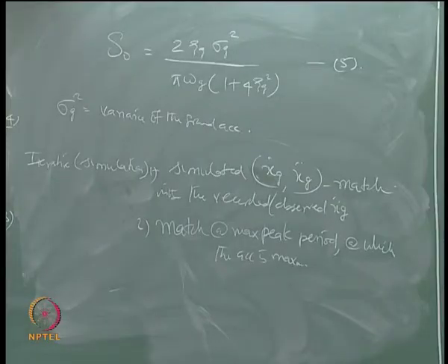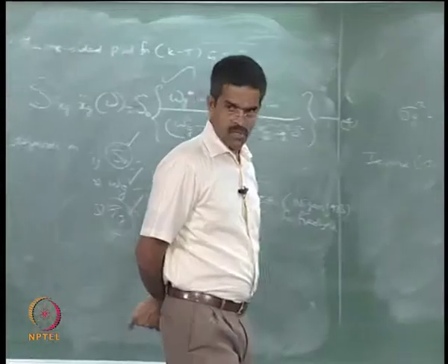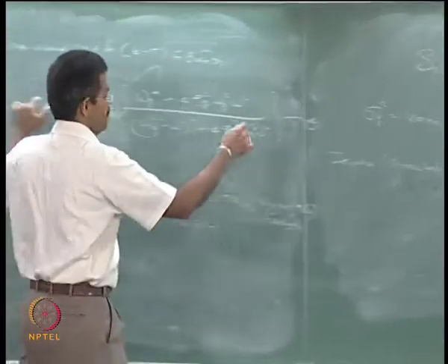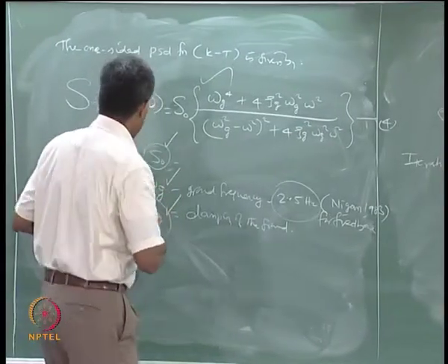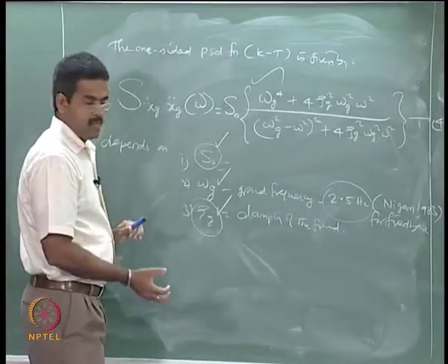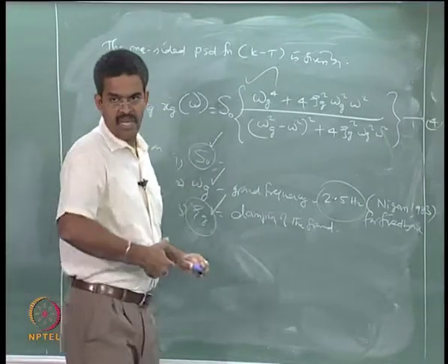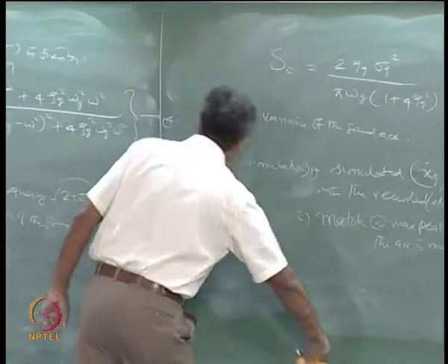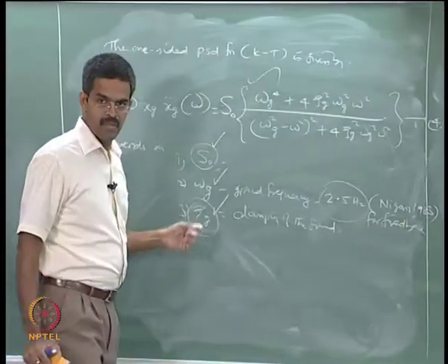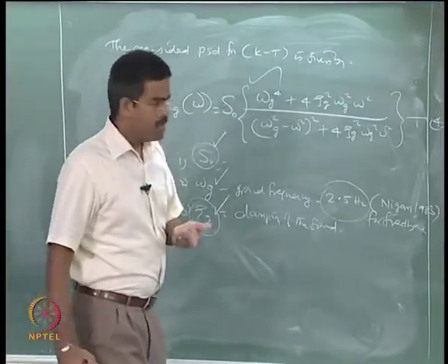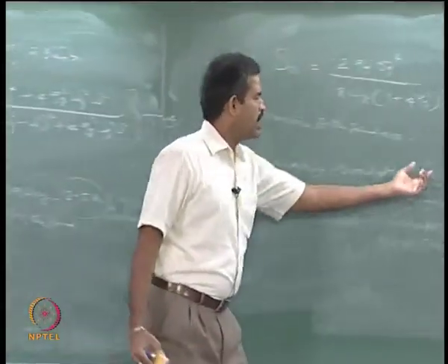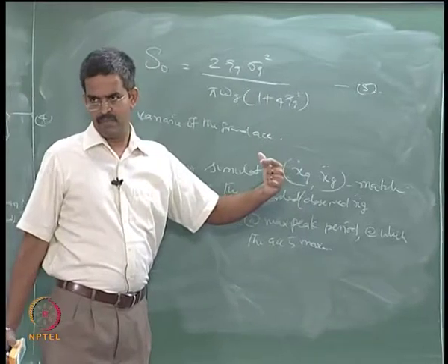So, seismic loads are not direct. Though you have a spectrum, the spectrum depends on 3 parameters. You must select these parameters at random. Now, the question comes, how do you select these parameters, which can help me to simulate a signal which is matching with that of the value observed at site?